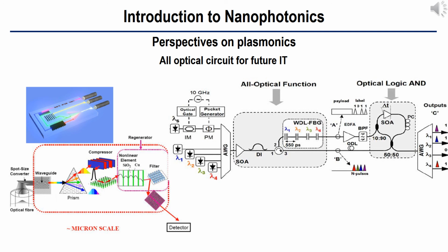But the problem is that a plasmonic waveguide with little signal loss is hard to fabricate. As described in the plasmon's properties, the surface plasmon polariton propagation length is limited and therefore, signal amplifiers should be accompanied. This requirement is not advantageous for sub-10 nanometer scale chips. And therefore, we need a sub-10 nanometer scale plasmonic waveguide for the all-optical circuit.